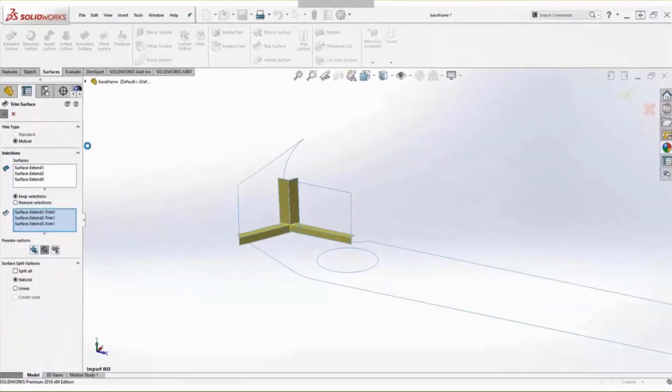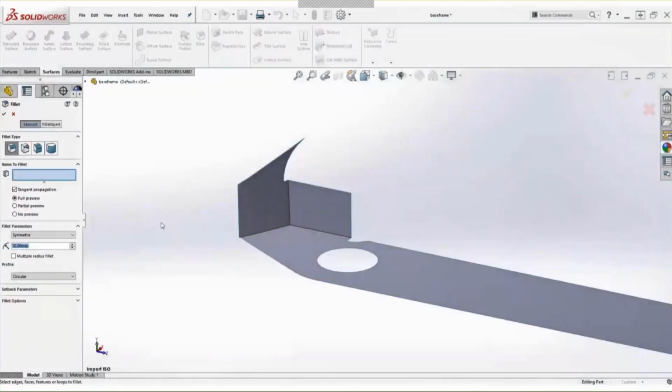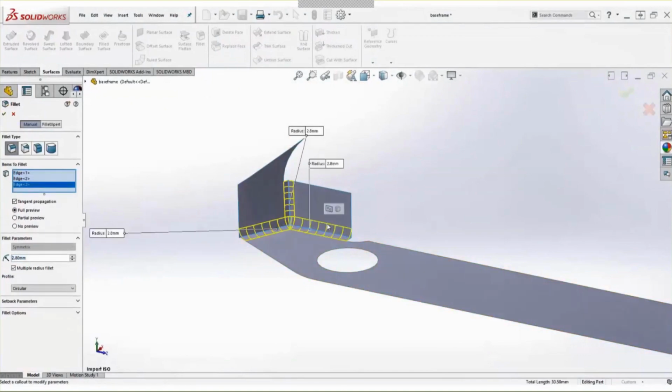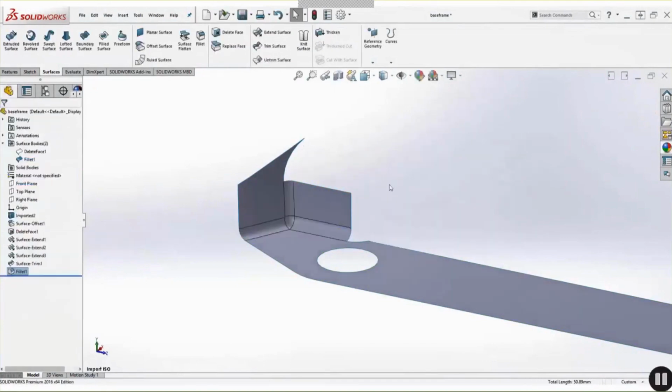So now with my hard corner surface body, I can add the multi-radius fillets I want into my corner. And prior to starting this, I checked what the radius values were using the minimum radius of curvature function, which is also available within the check command. So that's how I know what values to put in. And we can put those right in on the surface body as well.